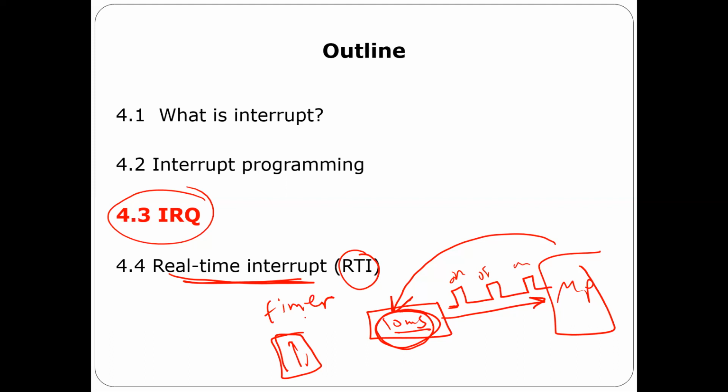What about IRQ? Okay, I'm gonna tell you. If this is the microprocessor, you have an external pin. As I told you, every time there is a falling edge here or low level, this is something you can select. This is what I said, configuration. You can select whether you want to trigger interrupts when there is a falling edge or when there is a low level.